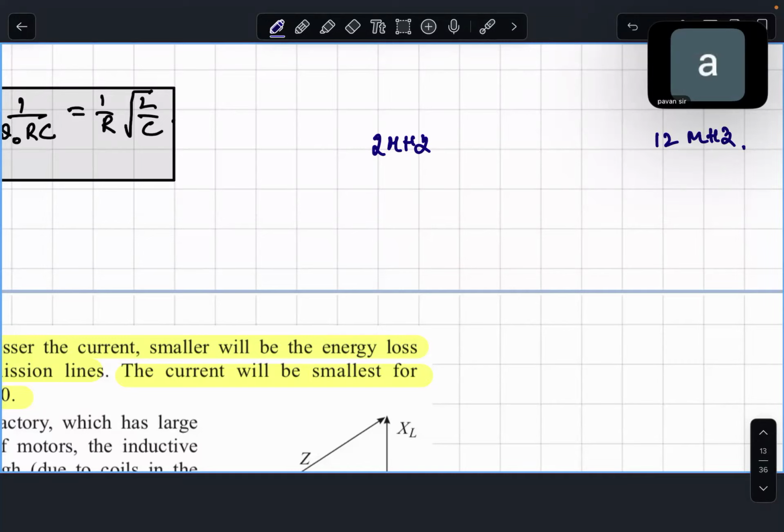Right. So how many divisions do you require? For safe side, divide it by 200, for example. By dividing 10 megahertz, 10,000 kilohertz, by 200, you get 50 kilohertz, 0.05 megahertz.